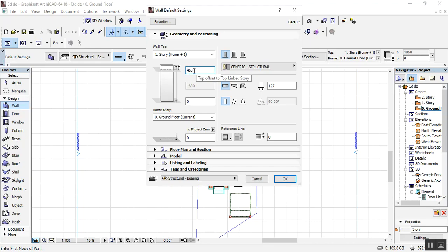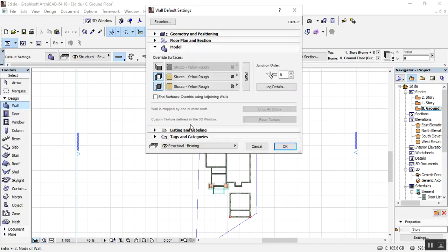450 is like what we want to create now is a ground beam. So here is going to be 0. Here's a 0 because this is the damp proof course we want to create. This is the DPC block. So we'll come down to this way. You put here 150. So let's say, assuming yours is like this, there are some whereby it's like this, you can't edit this part. So all you need to do is just activate the structural base, the composition. You put here to 150 millimeter. Put here to 150. You come down to the modeling.